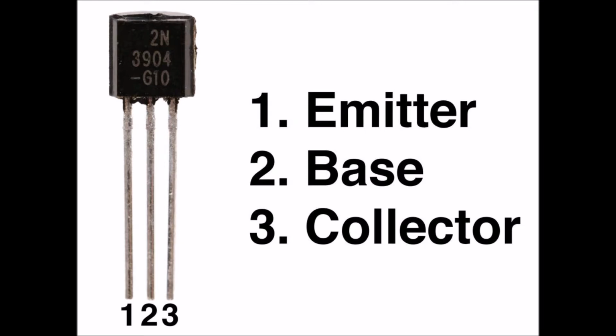PNP biasing. We can describe the situation inside a PNP transistor as we vary the voltage of the small battery or cell between the emitter and the base as a mirror image of the case for an NPN device. The diodes are reversed. The dual diode PNP model, along with the real-world transistor circuit, appear in figure 22.5. We can repeat the foregoing discussion for the NPN case almost verbatim, except that we must replace every occurrence of the word positive with the word negative. Qualitatively, the same things happen in the PNP circuit as in the NPN circuit.